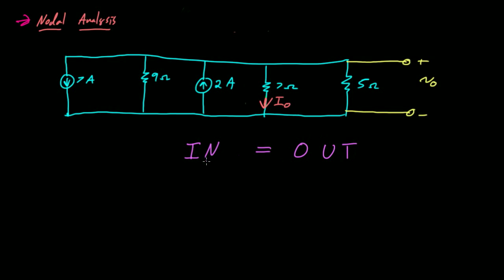Or maybe it would be better to say 5 gallons per minute flowed into one section of the hose. Then if we summed up all the water that flowed out of the hose, maybe split into a bunch of different sections, if I am providing 5 gallons per minute into the hose, then I've got to get 5 gallons per minute out. It's not like water is accumulating anywhere in a typical garden hose. The flow that I put into the hose has to equal the flow that I get out of the hose. And that's pretty much the way it works in a typical circuit.